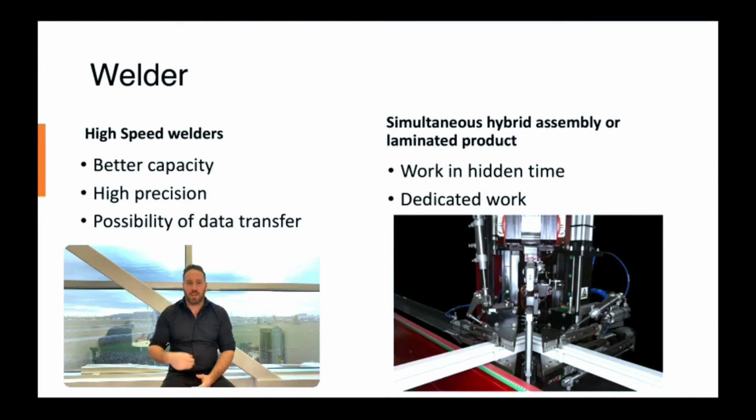Another thing that you can do on the welder now, you could have a drill that's been installed between 2 heads to do your mullion post on your frame. So the 3-head drill only applies to casement frames. But if you do have a welder that's dedicated to casement frames, this could be a good add-on as you're positioning your mullion as the window is assembled and being held at a square inside the welder, so you know that the precision is going to be 100% at that point.